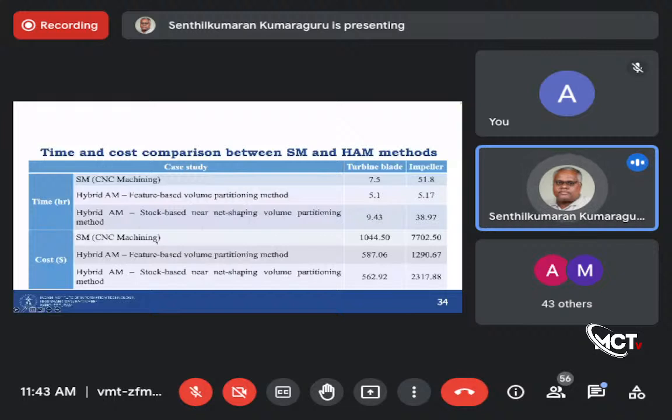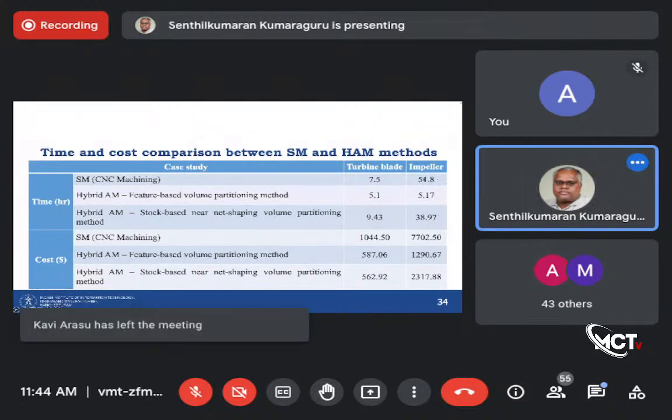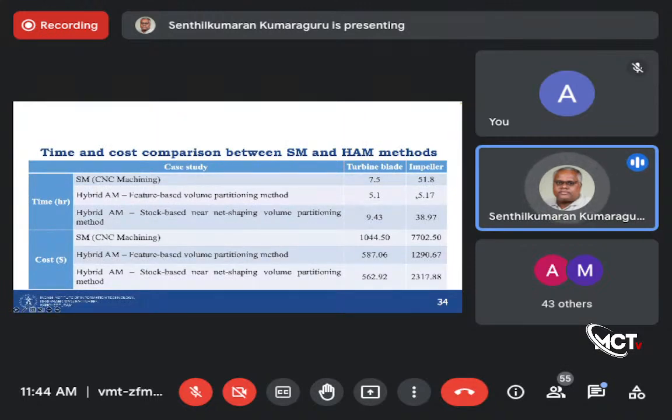So you can see the time is 7.51 hours. The time has reduced when you do the feature-based, but the time has increased when you do stock-based. So this 7.5 has gone up to 9.43. But if you look at the total time for the impeller, it was less than this. So for some parts, you can see that the stock-based came down comparatively with respect to the SM. SM is 51, but you see it's 38. It's much lesser, I think almost 12 hours lesser. You finish 12 hours faster with hybrid than with subtractive machining.